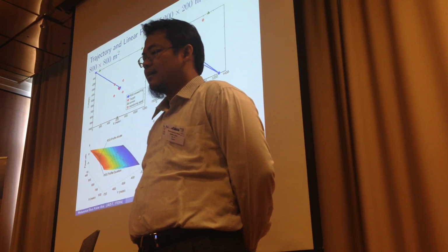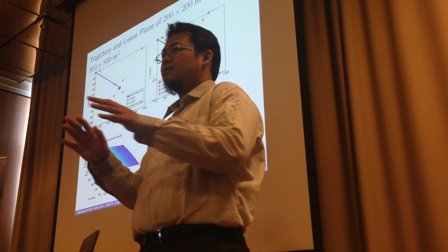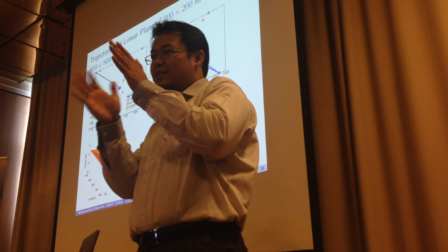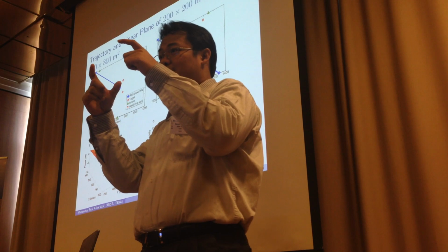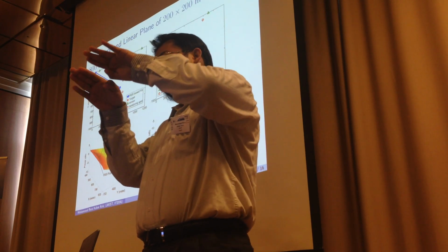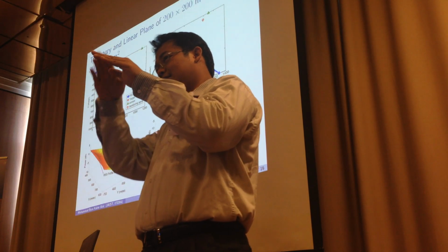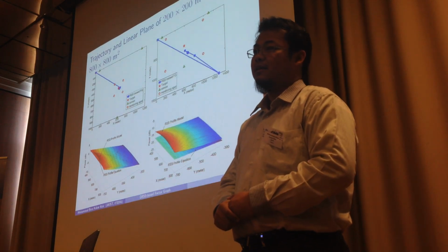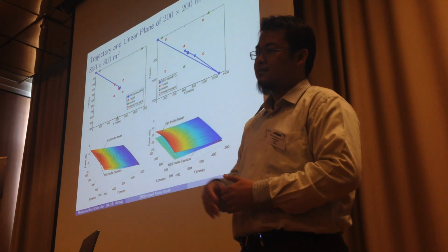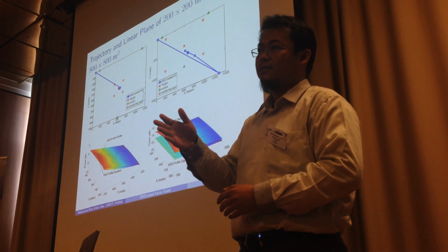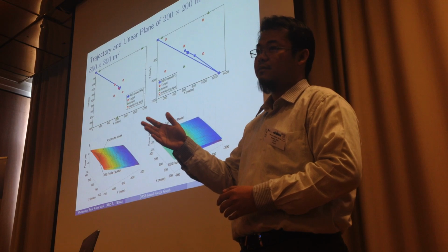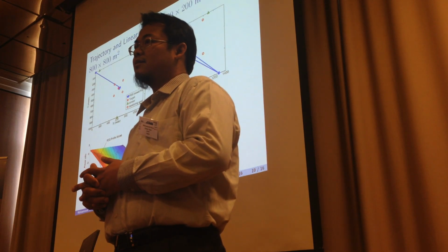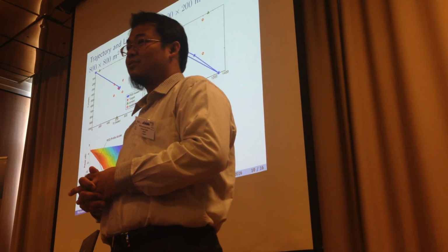In the indoor case, the literature uses a very small monitoring spot area, and they can make the approximation of the shadowing of the measurements, and also the instantaneous fadings, and these become the samples, which follow a Gaussian distribution. This is what I found in the literature for the indoor case.